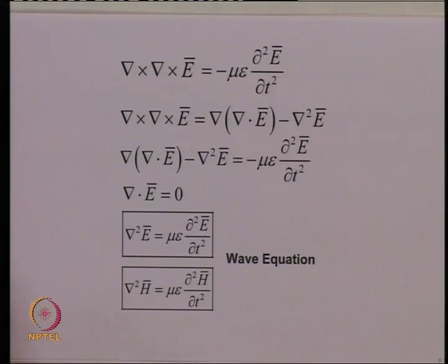So, now what we do is we try to solve the wave equation with the physical understanding which we have developed using the ray model, apply appropriate boundary conditions to this, and then get the analytical form of the electric and magnetic fields which would survive inside the core of the optical fiber.